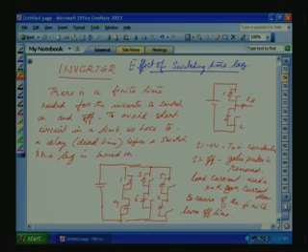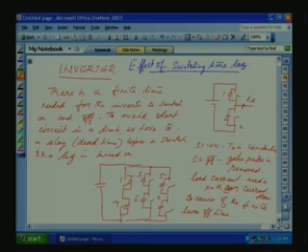In the negative case, current will be flowing through the diode. The diode, the moment it is reverse biased or the current is removed, will quickly switch off. But the devices, transistors or MOSFETs, require some more time to turn on and turn off. So when S1 is on, in this case, current is flowing through the transistor.